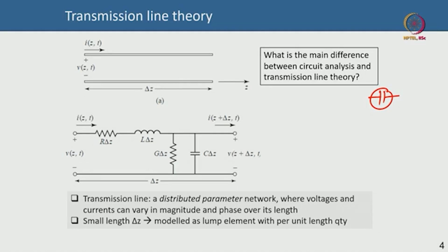So, you put that, it is a lumped element. It works okay for analog low frequency signals, DC, etc., but even digital, for instance. The problem is when you have RF signals, the wavelength of the RF signal is quite small. So, it approaches the physical dimension of a capacitor or an inductor or a resistor. So, this lumped element treatment is no longer valid, because the magnitude of the current or the voltage and the phase of the current or the voltage can keep changing at different points on the line.